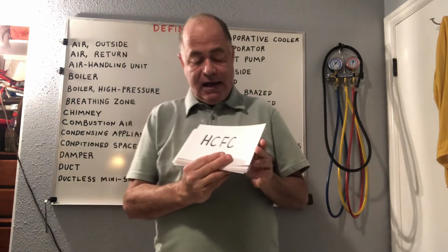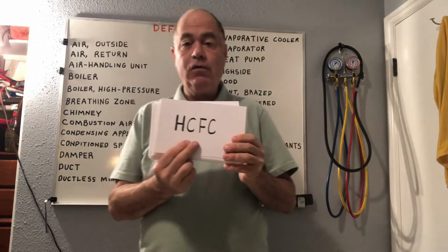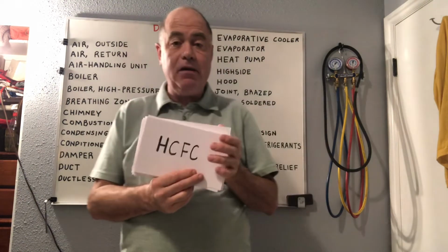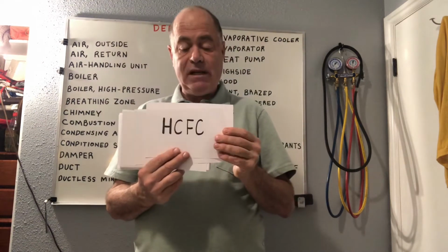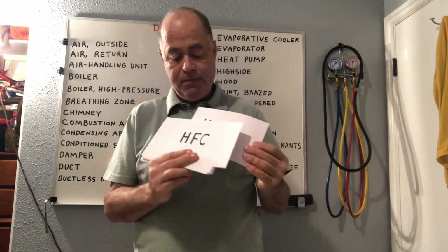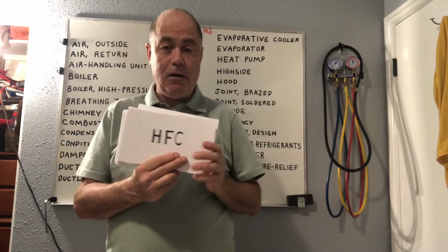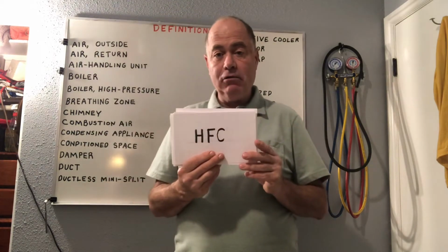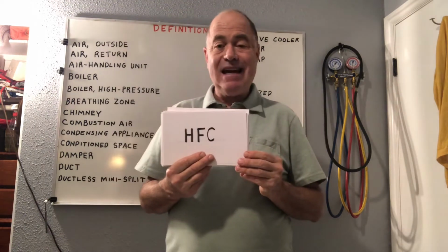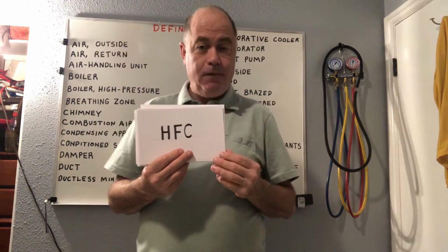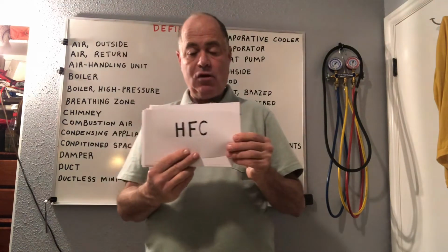And with that, HCFC, hydrochlorofluorocarbons, is an older type of refrigerant. The most popular was and is R22. Okay. This is hydrofluorocarbons. These are probably the most popular refrigerants here in 2021. This would be things like refrigerants like 404A, 134A, 410A.